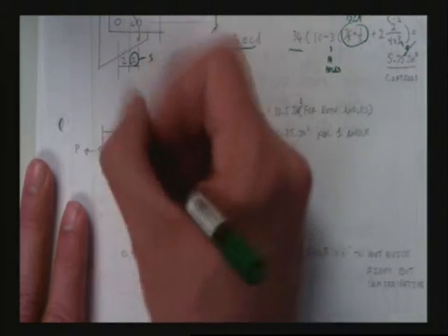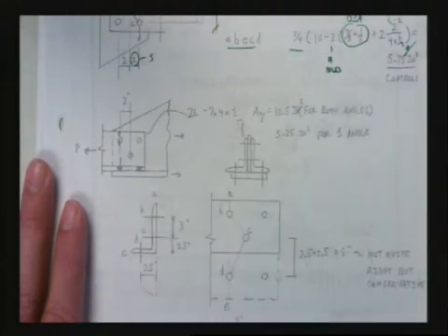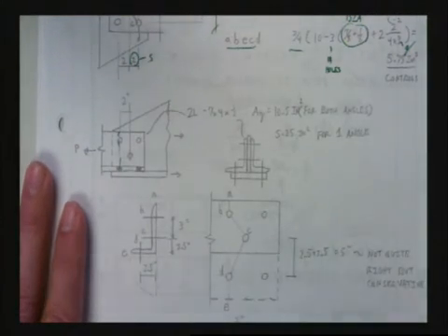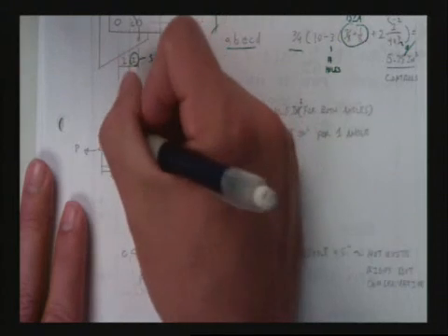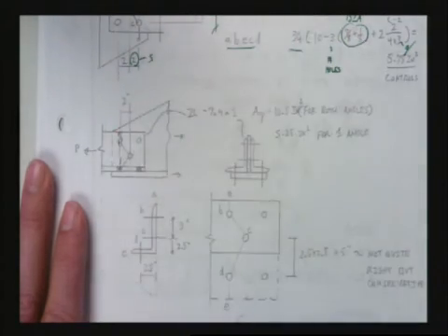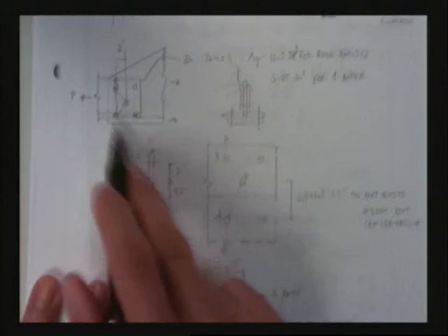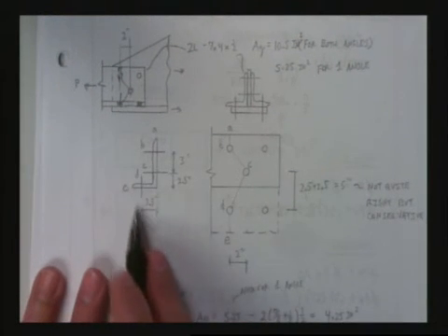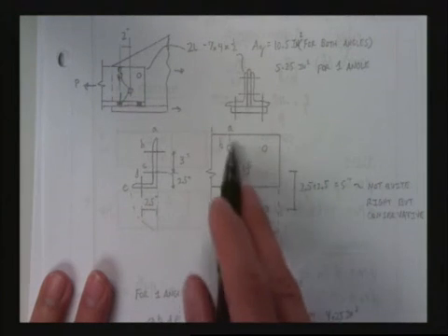Well, one failure mode would obviously be straight across. Another failure mode is possibly down, over, down, and then straight across. That doesn't seem too hard. We can take this plate, imagine flattening this out, rotating this, and then drawing our failure modes.